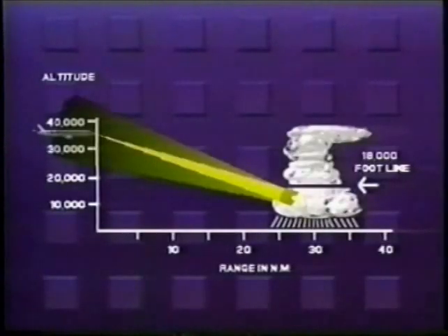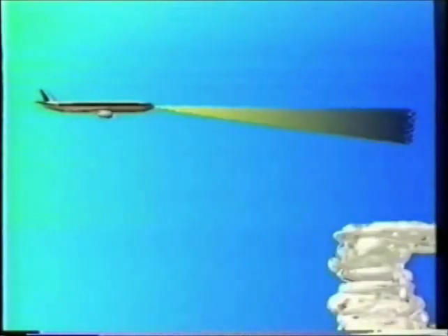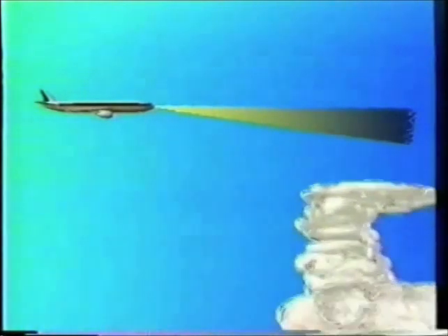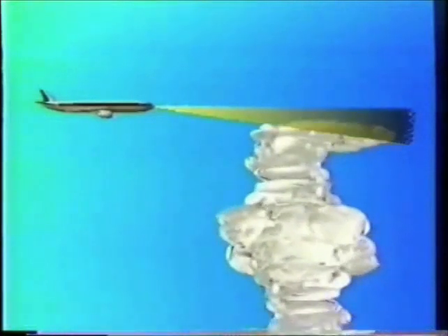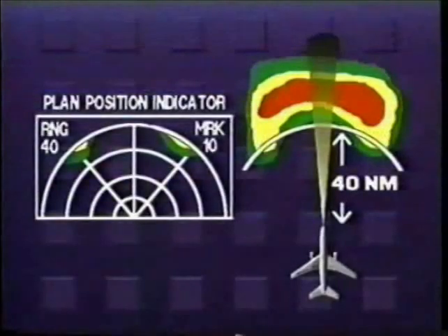Whenever an en route storm is being evaluated, aggressive use of down tilt is necessary to direct the beam into the lower 18,000 feet of the storm. A subtle form of overscanning can result if a low-altitude thunderstorm is rapidly building. Some convective storms grow at rates of up to 8,000 feet per minute and can rise up under your flight path as you approach them. If convective activity is high in your area of flight, it's a good idea to lower the beam from time to time to look for rapidly developing storms.